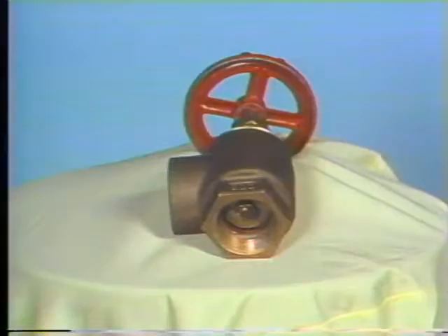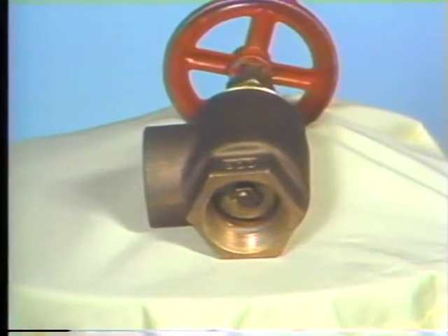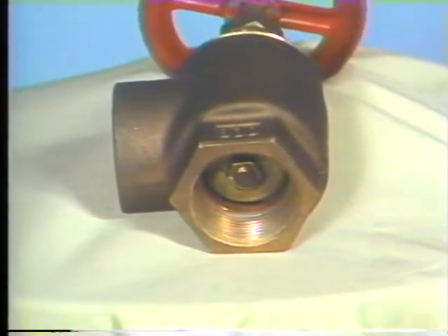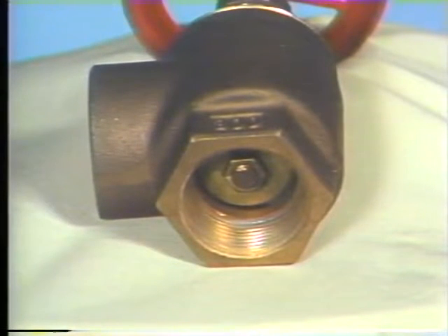Your text presents 2 other methods, but the three we will discuss are the threaded joint, the flanged joint, and the welded joint. This is a valve with a threaded joint. A threaded joint simply has threads like a bolt or a nut, and the parts are threaded together. This type of joint is used primarily for small piping of 6 inches or less. This is the symbol for a threaded joint, a single short line that crosses the pipeline at a 90-degree angle.